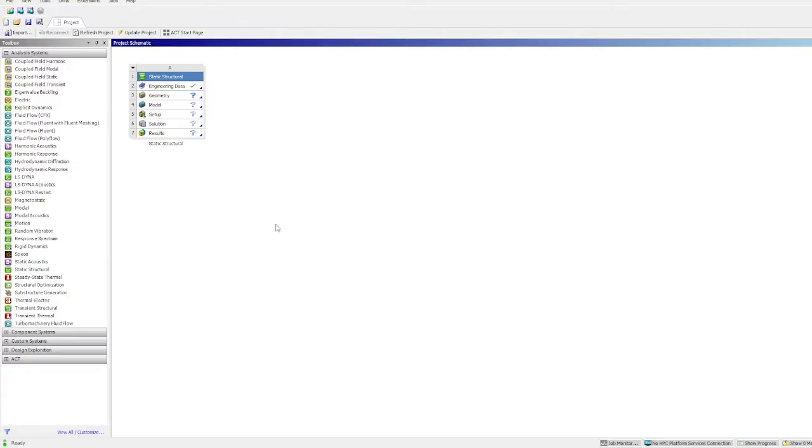This window represents all of the things we need to complete our study. Up on top, it has the materials library, and then we go through and assign the geometry and assign our loading and our meshes and all of the things needed to get a result. Whenever you see a check mark next to something in an icon like this in Ansys, it means it's ready to go. A question mark means that we have to define it. A little X means it's not defined.